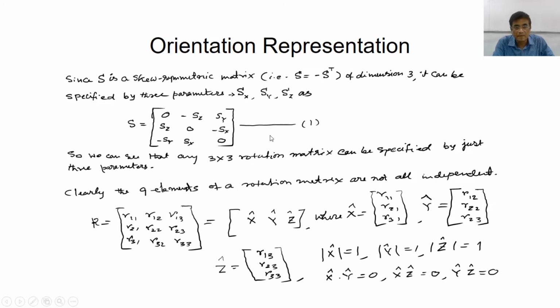We can also, instead of keeping the raw 3 by 3 matrix, observe the nature of the matrix and put the necessary constraints, and we will come across 6 such constraints, because ultimately I have only 3 independent parameters, theta, phi and psi, and R has 9 elements. So we can constrain them appropriately.